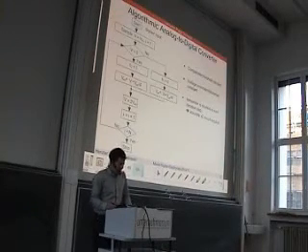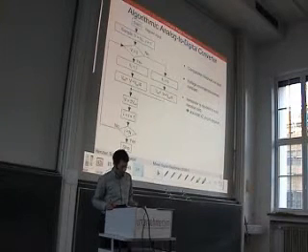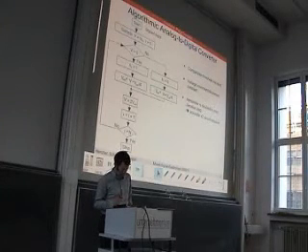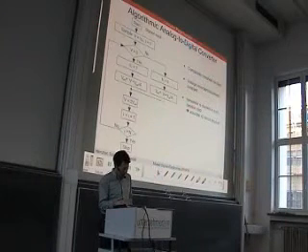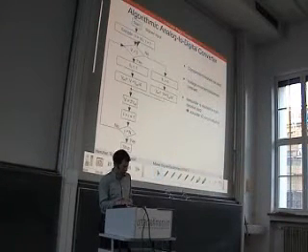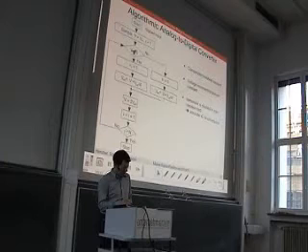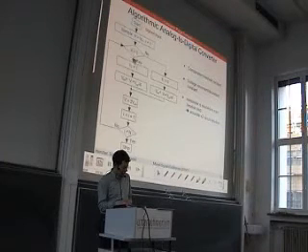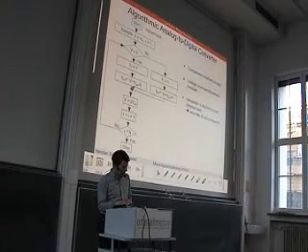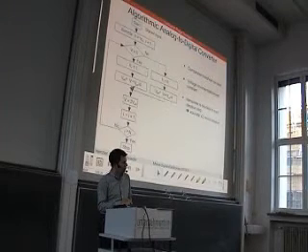The algorithm that we discussed last week was for this algorithmic analog to digital converter. Step 1 was to sample the input voltage. Then we compared this input voltage to 0. If the voltage is larger than 0, then we set the most significant bit to 1, and we decrement the internal voltage by Vref over 4.